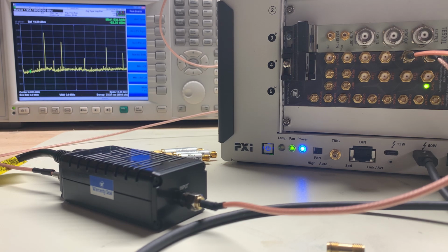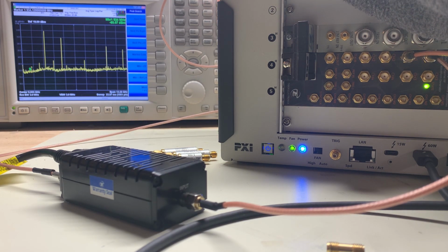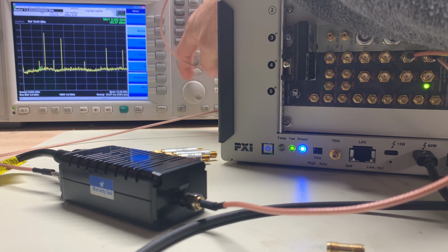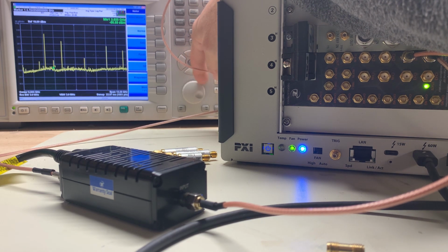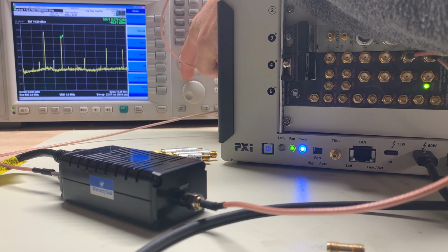And there we have a frequency. So I've got the center frequency set to 3 gigahertz. So I've got 3 gigs. I've got, let me get the marker. So this is my main signal here. 3 gigahertz. Well, it's 3 gigahertz minus the 75 megahertz. And then I've got another one here at, let me get the marker on top, at 5 gigs.